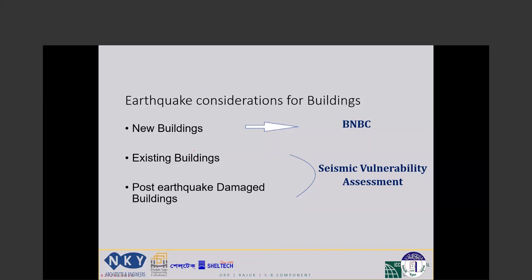Before it was pre-standard, it was some recommendation. But buildings that experience damage are even more difficult to model, because from the cracks and the residual displacements, you should see for each element how much you should reduce the stiffness, how much you should reduce the strength of that specific response parameter, and how much you should reduce the ductility capacity of this element because of the damage that is observed right now.